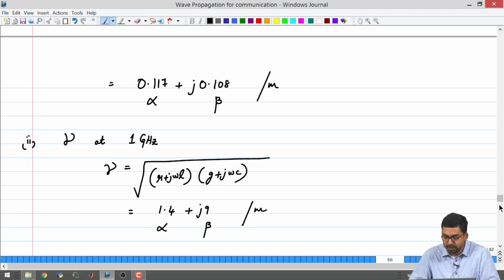The only way to deal with this in practice is probably to build better cables. This is one approach. The other approach is to have some amplification in your lines. For example, when your signal deteriorates over a distance, at that distance you keep some kind of an amplifier which converts, say, electrical energy and transfers it to the signal, so you have a higher magnitude of the signal that is traveling. So, you will have in some way some repeating amplifiers of some kind in your transmission line.